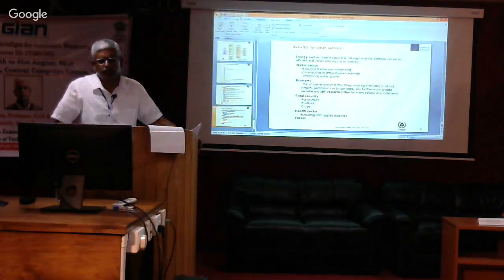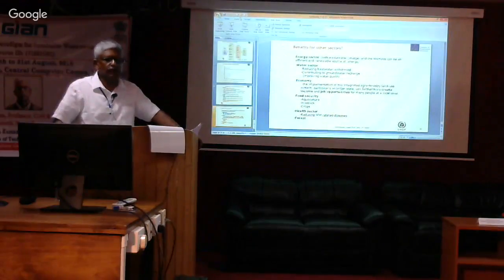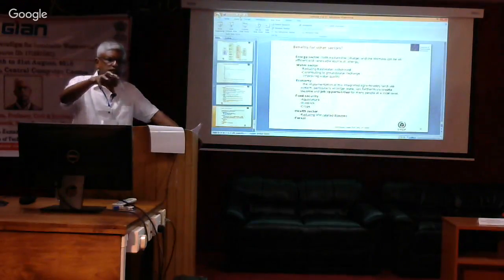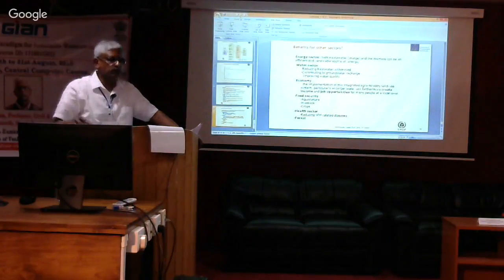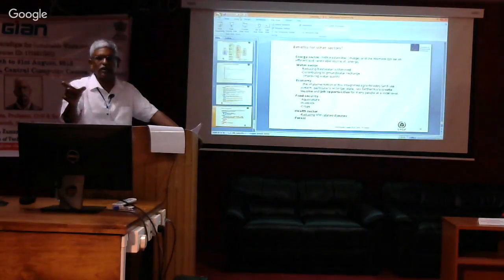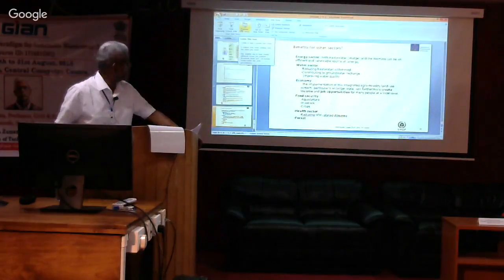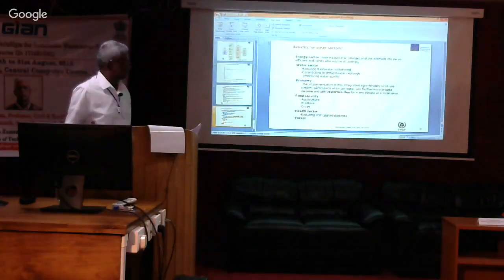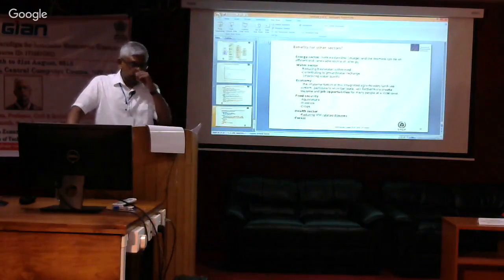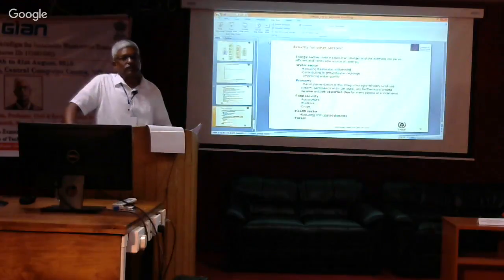What we now typically mean by decentralized is take this wastewater, you treat it at the source, but it involves much more than just a septic tank. Typically, it will involve what is known as a septic tank, and then what we call a SAS, a soil absorption system. And in the soil absorption system, we can denitrify, for example.